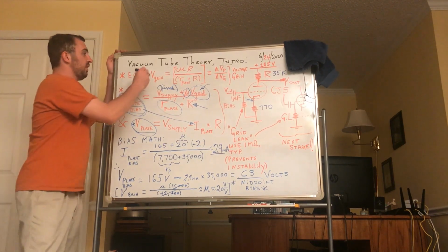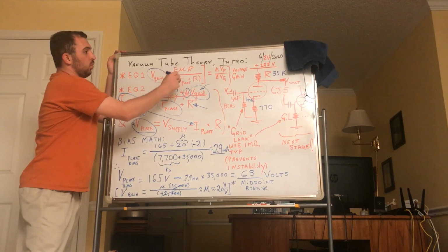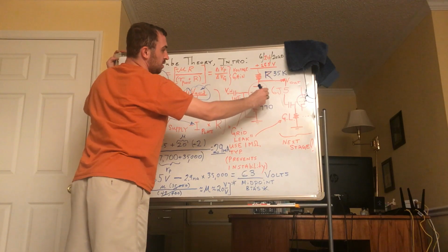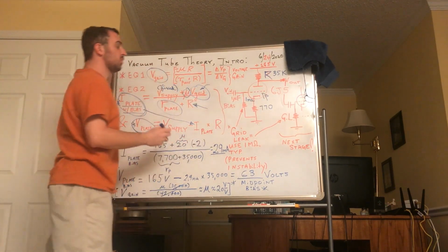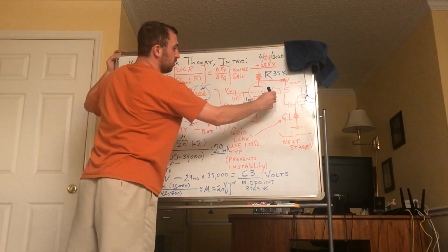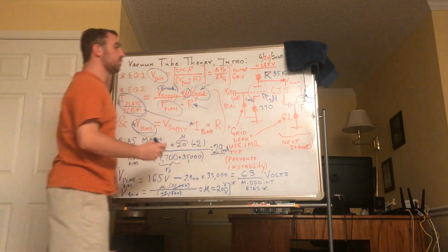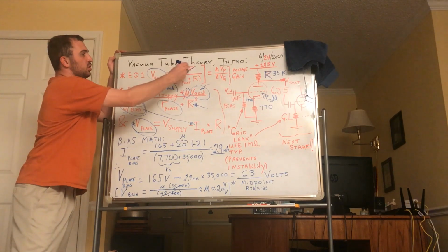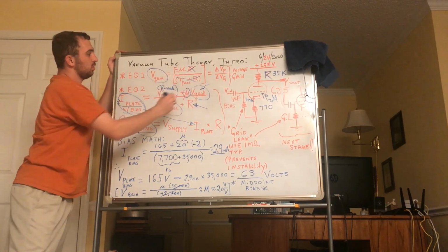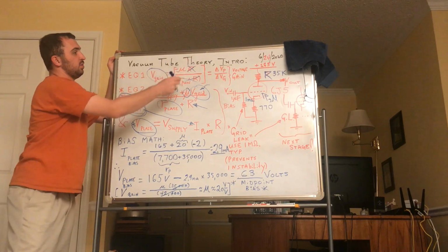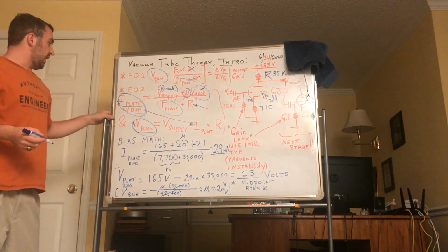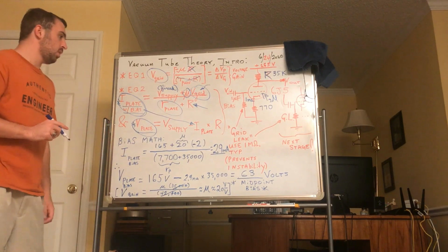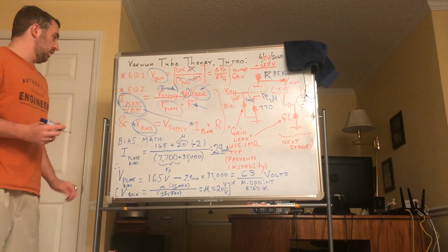And then you can manipulate this equation here, where R is this resistance and R plate is inherent to the tube. R plate and mu are the two factors. And then you would find your voltage gain, which when R is large is approximately mu, because these cancel to give unity. Okay, we've derived these, and so the listener can understand where they came from. So let's take a typical circuit.